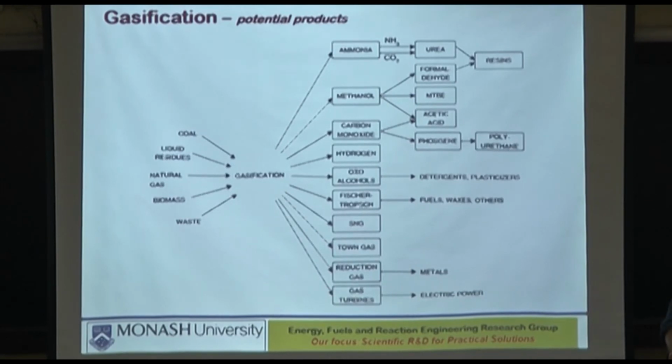Where you introduce the oxygen is extremely important, because if you are introducing oxygen at such a high temperature, near where it sees only hydrogen and methane and CO, the poor carbon will have no chance of getting any oxygen. It will all be scavenged by these three molecules, right? So that's the gasifier design aspect. So we'll come to that.